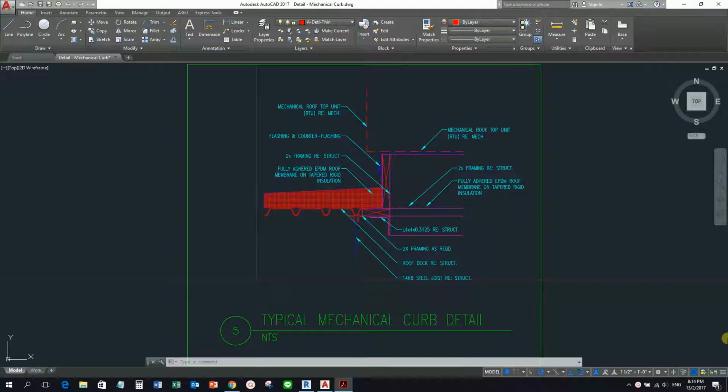So for today's lesson, I'm going to teach you how to import and edit the drawing details in Revit MEP or Revit 2017. Okay? So this lesson describes how to import and edit DWG details in Revit because engineering firms maintain files in the form of libraries of commonly used drawing details. It's true. So you can import these details into projects and edit them as required. So importing and editing typical details enables you to save time and effort and avoid duplication of work.